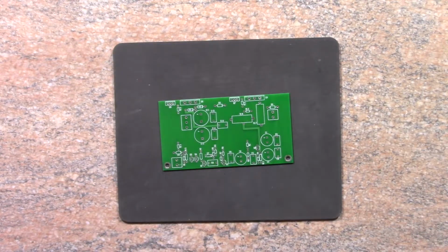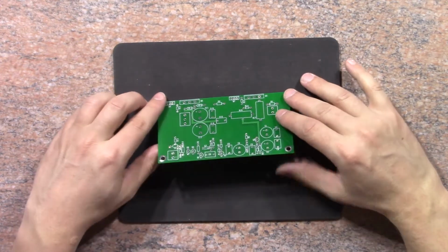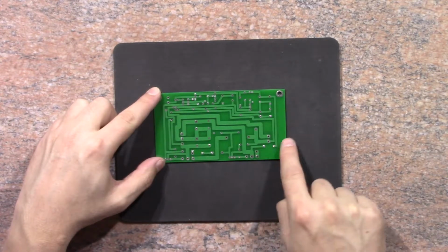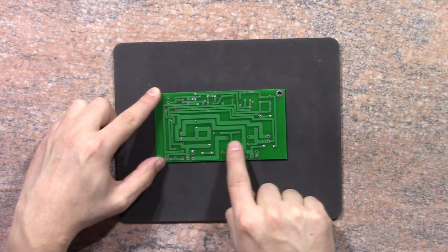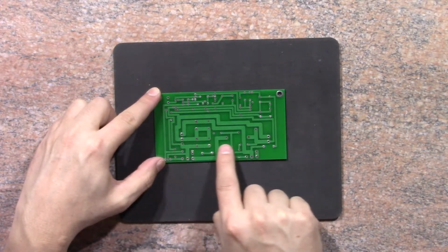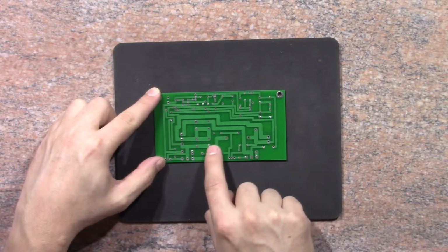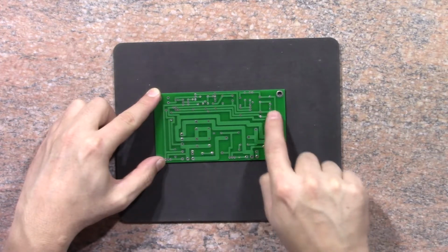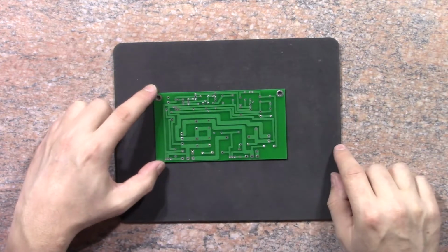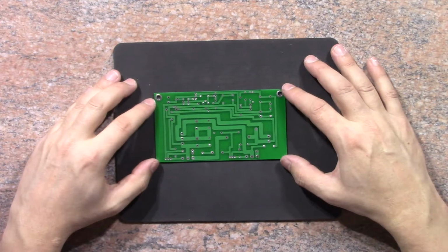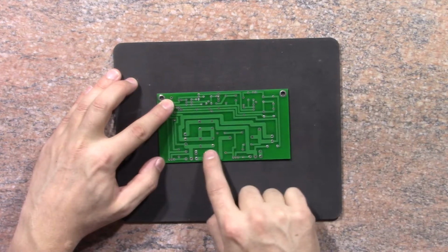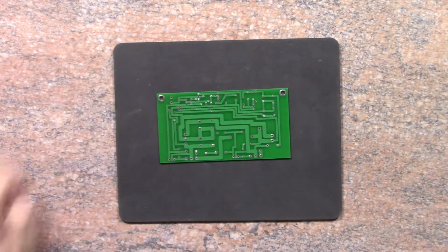Next is the power amplifier card. And the only special thing to mention here is that the tracks are really thick. This was also made on a PC board with the thickest copper available. It's a 35 micron copper laminate, and you can actually feel the thickness of the copper. That's because this amplifier could possibly produce up to 4 amps RMS, and you need lots of copper to be able to carry that sort of current.